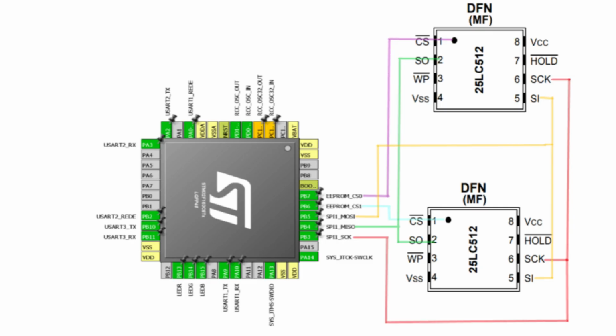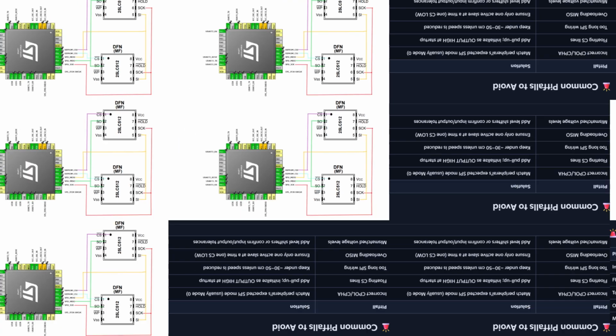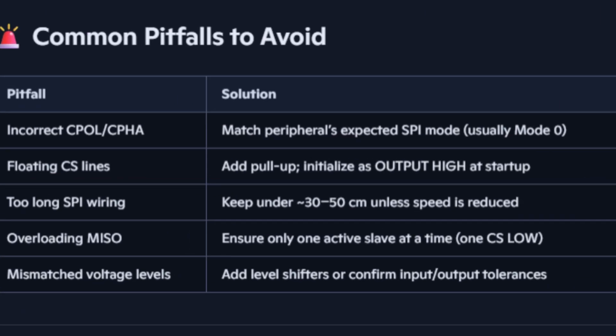Okay, voltage, signal integrity, decoupling, pull-ups. What about routing the shared lines? Good point. Hardware routing. MOSI, MISO, and SCK are shared. Route them as parallel tracks where possible, ideally with ground traces interleaved or on an adjacent layer. Try to keep their lengths roughly matched, especially SCK and MOSI, to minimize timing skew. Keep them away from high frequency or high current traces.